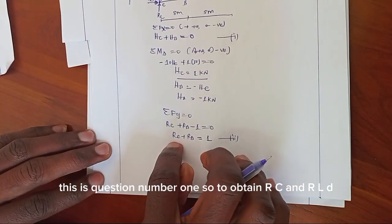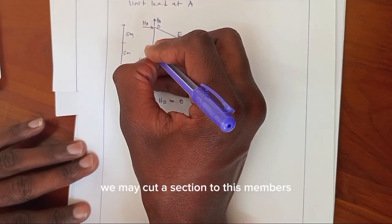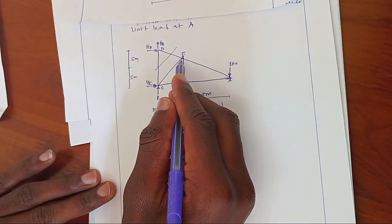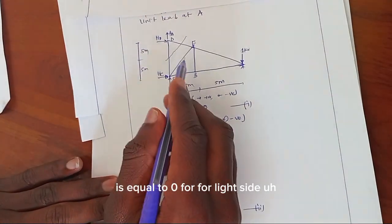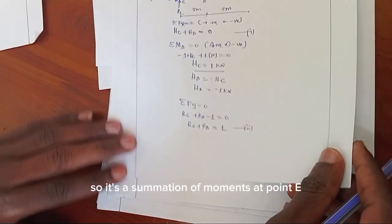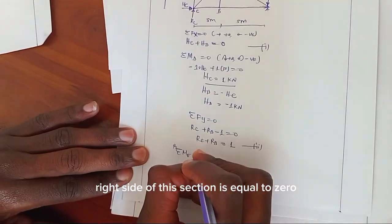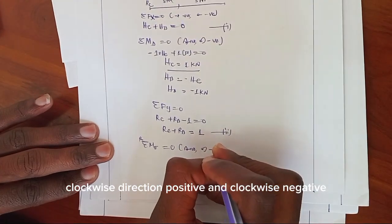So to obtain LC and LD, we may cut a section through these members. After cutting a section, we take summation of moment at this point is equal to 0 for the right side of this section. So summation of moment at point E, right side of this section, is equal to 0. Clockwise direction positive and anti-clockwise negative.